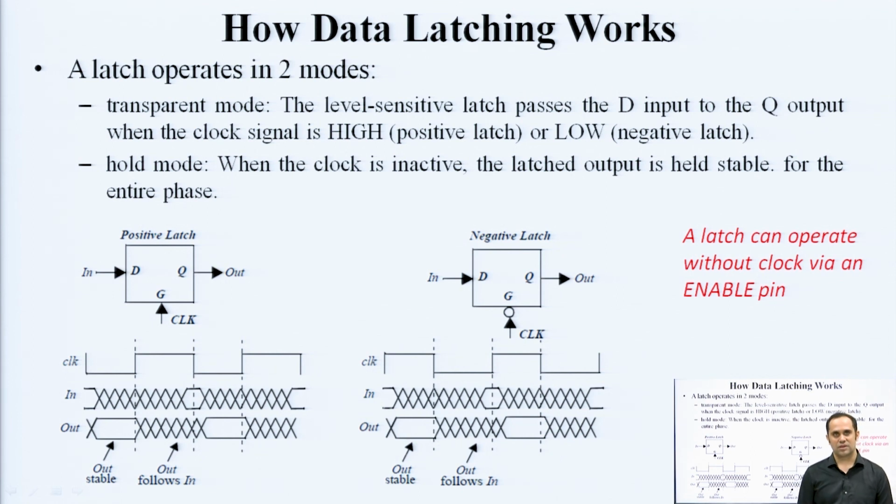triggering occurs. So, the major difference being that a latch can work without a clock, but it still needs an enable signal, and that enable is level dependent, it is not transition dependent. As soon as the correct level is available at the enable or clock, as soon as input changes, output will get refreshed, of course after some finite propagation delays, but that activity will keep on going.